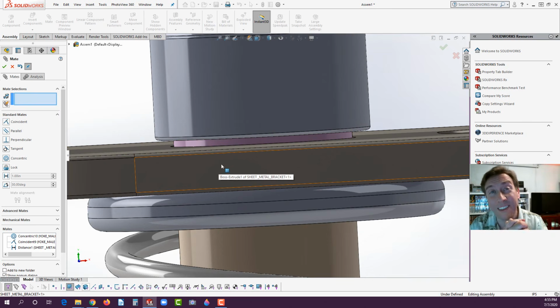That's what we added. Now that's a very realistic approach. Remember, when you're designing things, you design in tolerances. And SolidWorks does actually have tolerance stack analysis, so you can do Monte Carlo simulations on stack analysis, roll up, roll down. We're not going to cover that. That's a whole module in and of itself. There's videos out there, I'm sure. I don't ever cover that, although I got training for it. It is really neat stuff, for those of you who need to do tolerance stack analysis.